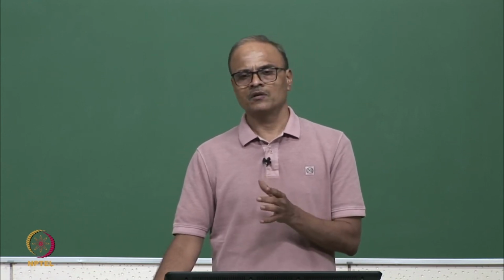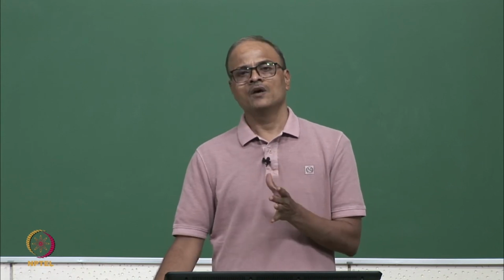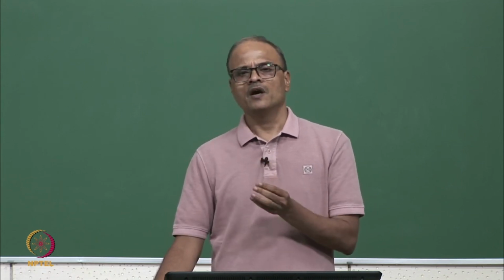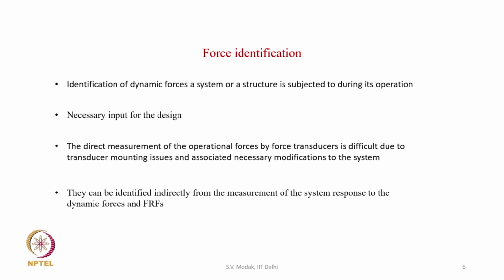So, it does not depend on direct measurement, but it performs indirect identification from the measured responses and measured frequency response functions. So, these forces can be identified indirectly from the measurement of the system response to the dynamic forces and FRFs. Instead of measuring the dynamic forces, what we measure is the response. Measurement of response is much easier as compared to direct measurement of the forces.